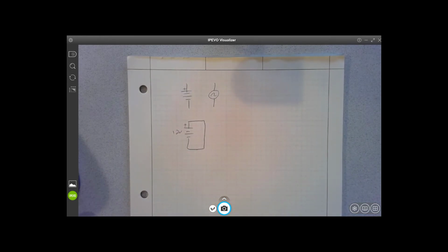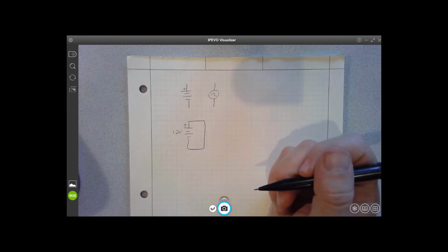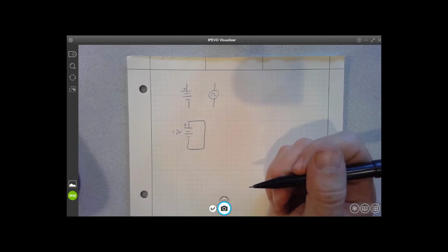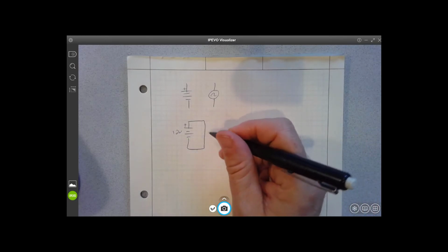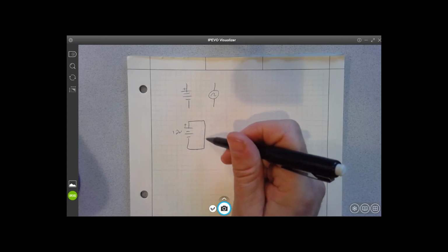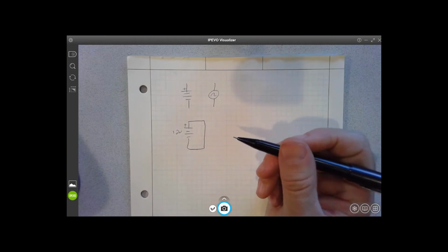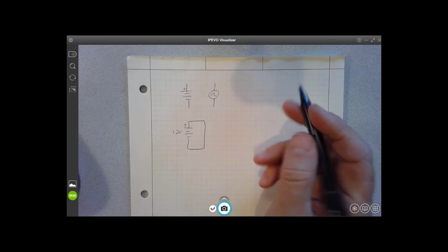That supply wouldn't last very long unless it was fused, because we've now connected a path from one end to the other with essentially no resistance in it. So it's going to flow as many electrons out as it can in a hurry, and most likely it will either burn up the power supply or melt the conductor. So we need to add some additional components to have a circuit that's actually useful to us.